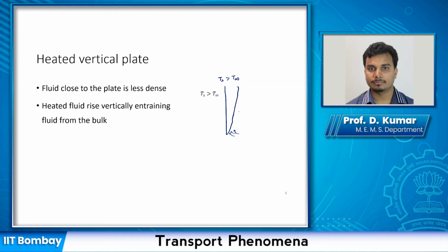Okay. Now the nature of this boundary layer is different. The way we have been defining boundary layer is that the velocity, over here it should be, as v infinity. In this case, there is not, it should be almost equal to 0. What we are saying is that there should not be relative velocity between this and this, right? Just at the boundary. Since this is 0, so this has to be 0. So if we are looking at the velocity profile, it has to be 0 here.